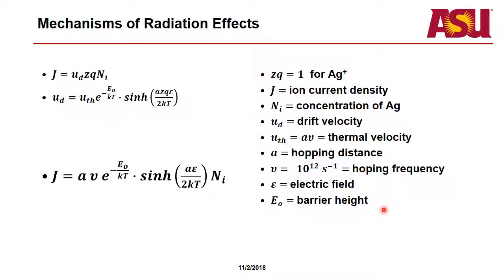And then even for the beta phase, it's about 0.2 to 0.3. So there's actually not a whole lot of difference in that barrier height for hopping. And if we assume also that between the beta and alpha phase test, this kT value is going to be static because we're not changing the temperature of the test. We're applying about the same field for both throughout the tests. We're applying the same pulses, the same IV sweeps.